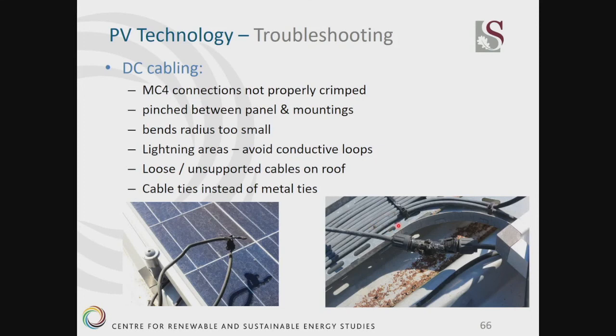In this cable tray, there's no problem using a plastic cable tie. Although it might decay and might go off, this cable tray on the roof will be closed from the top. So these cables will also not be exposed to any UV, and the same goes for the cable tie.